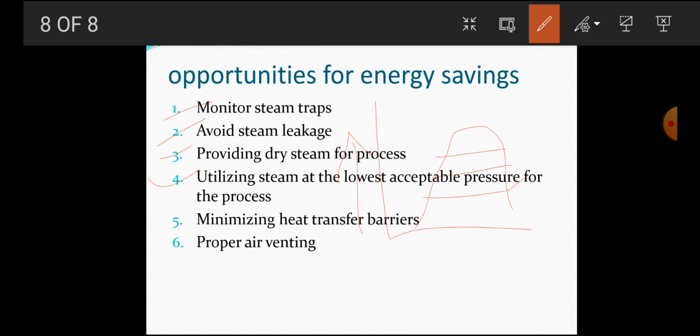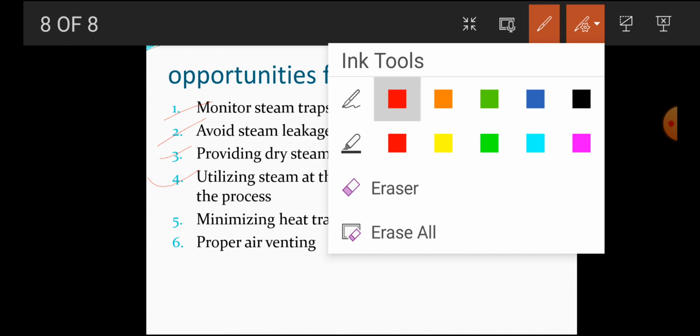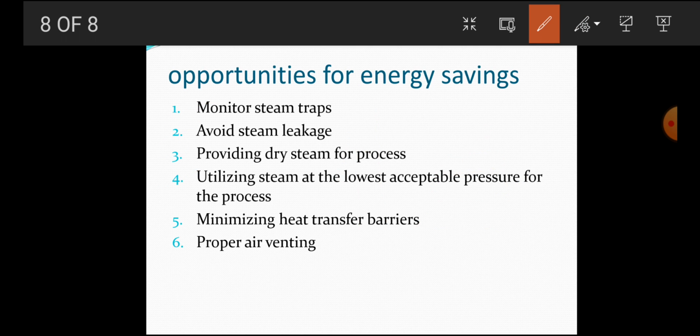The amount of latent heat is reducing as the temperature and pressure increase. It is only the latent heat of steam which takes part in the heating process when applied to an indirect heating system. Thus, it is important that its value is kept as high as possible.